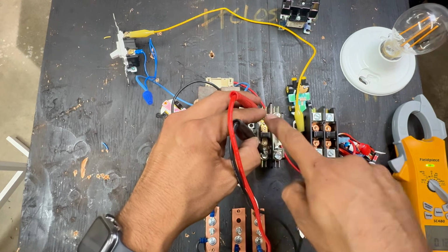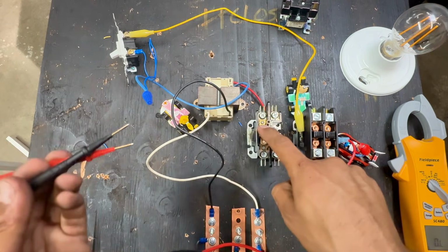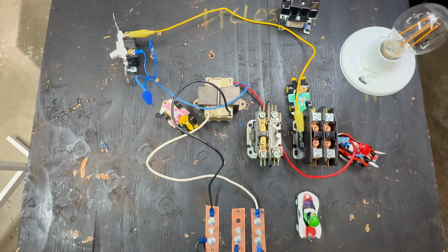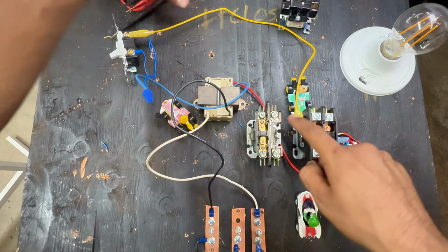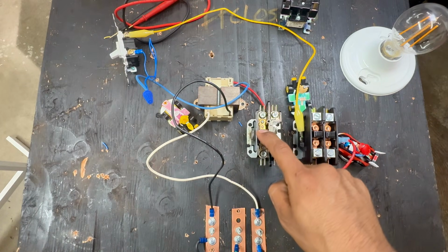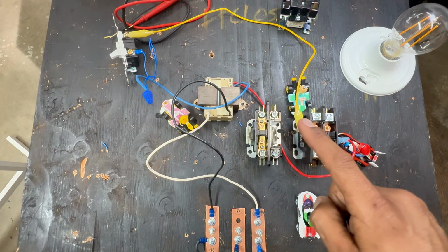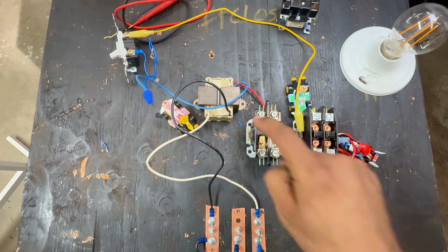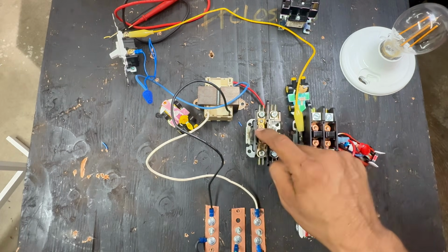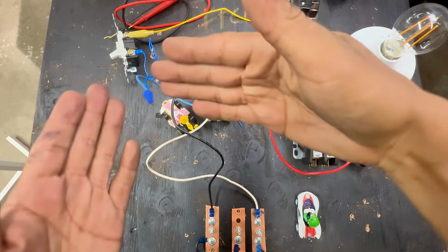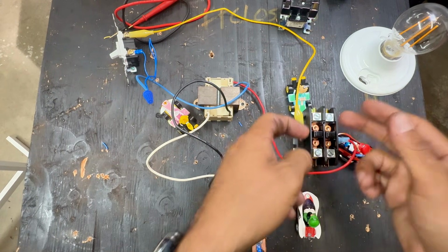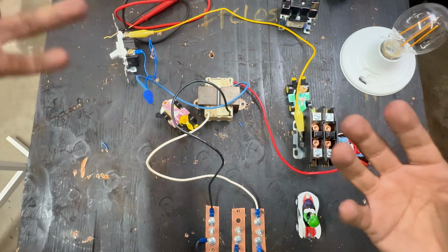But you're not going to do that manually, because this contactor we use when we have a call for cooling. You're not going to be saying, Mrs. Applebottom, do you want cooling? Yes. Okay. Thank you, I'm okay now, I don't need any more cooling. And then 30 minutes later, I need some cooling, and then you're going to push that. You're not going to be doing that, right? That's too much work. So this is where you use a thermostat to redirect the 24 volts to send power, as we will see in the schematic.